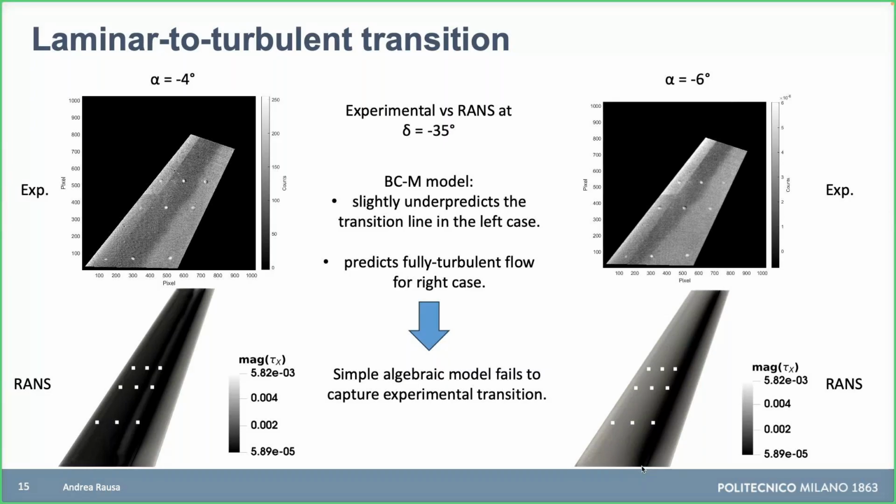Whereas for RANS, using the Spalart-Allmaras model, we see that we actually don't capture this transition. So here we don't have transition, here we are fully turbulent. So we kind of miss this modeling, but again, using maybe a gamma-Re-theta model and SST, we can maybe improve these results here.